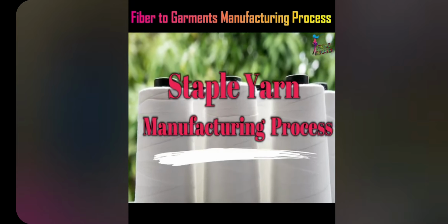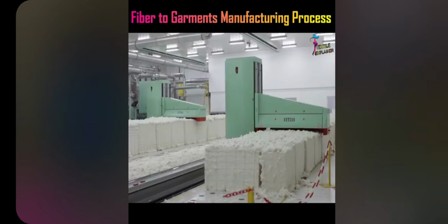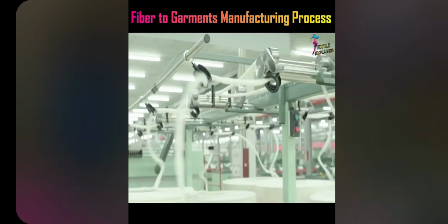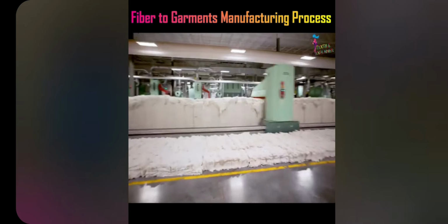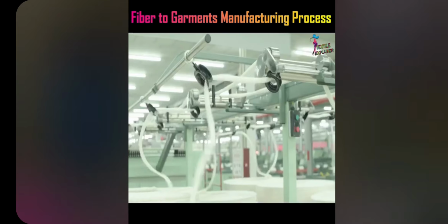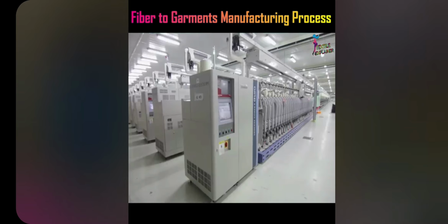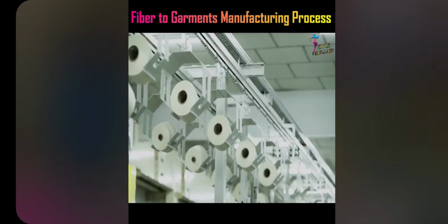The process of staple yarn manufacturing starts with opening a bale of fiber and cleaning the impurities on the surface using a bale opener machine. Then the process is followed by a series of continuous operations such as blending, mixing, carding, drawing, roving, and spinning. And finally, we get the cones of yarn, which is used to make fabric.